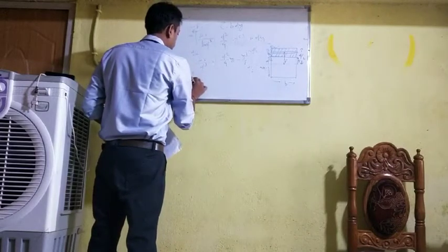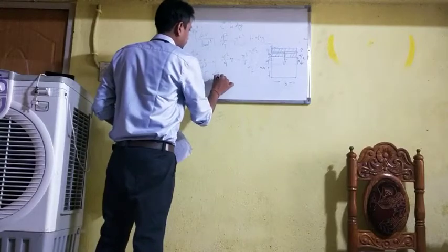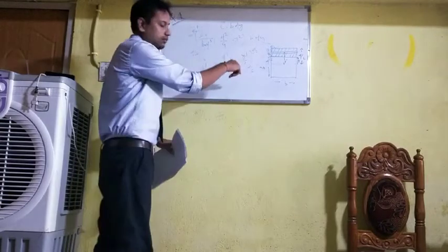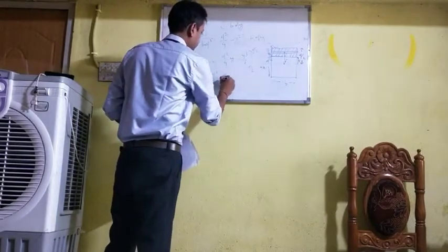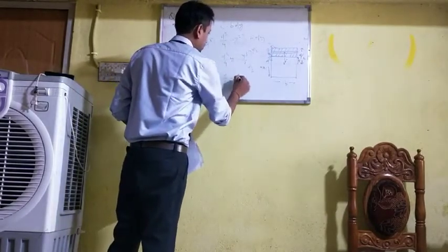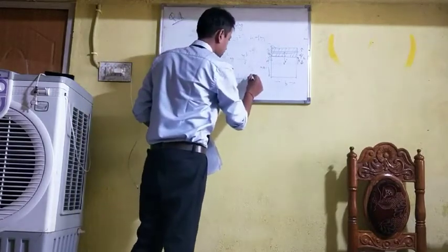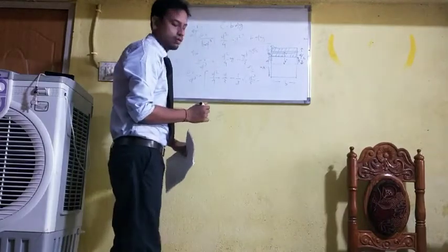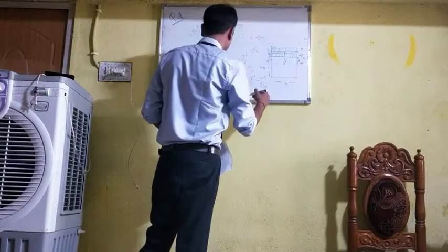So this is equal to 6V upon d cube into this is d square upon 4 and here is y. So we have to put the limit in place of y. This is d by 2 minus d by 6 and that is equal to d by 3, minus this is 1 by 3 into y cube. Y cube means d by 2 cube, that is d cube upon 8, minus d by 6 cube, that is equal to d cube upon 216.